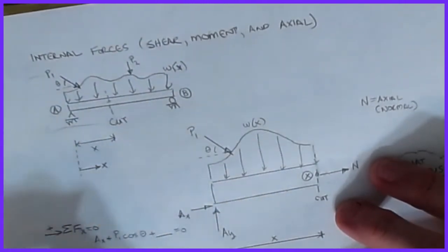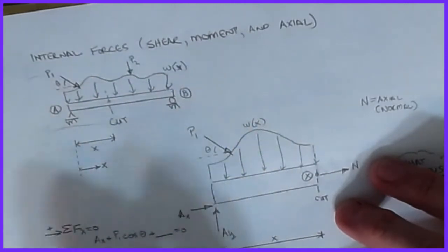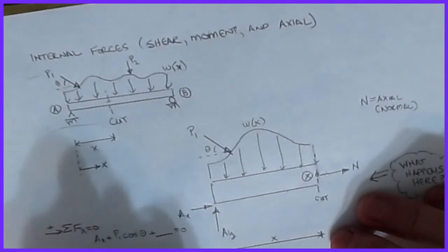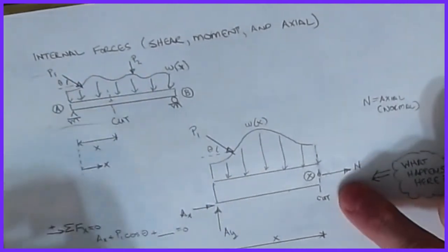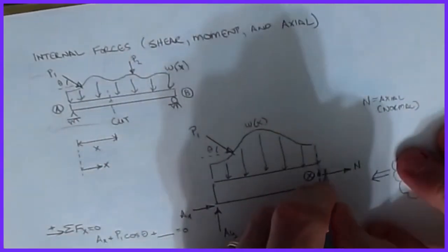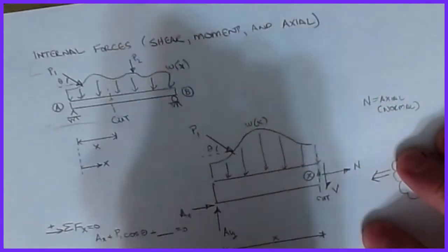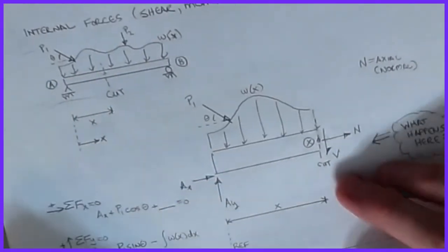But then if that's the case, if I have an Ay value in these, it's possible that this doesn't itself add up to 0. So what we're going to do is add some internal effect here that represents what's happening at the cut. This one's a little different, and I'll explain the sign convention in a second, but we're going to draw it down on that particular cut location.